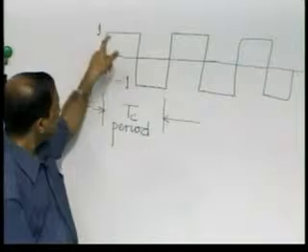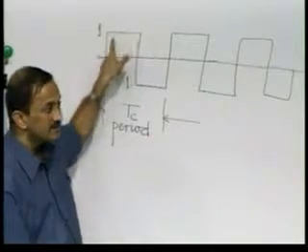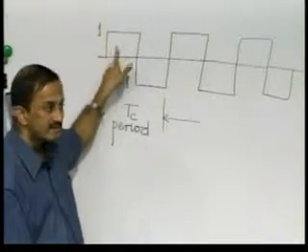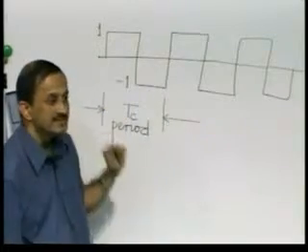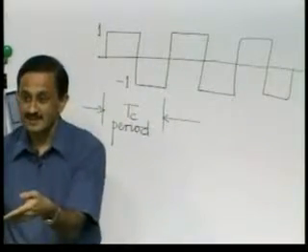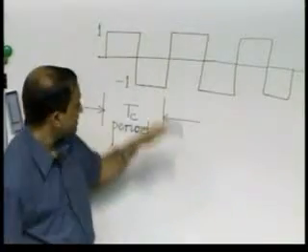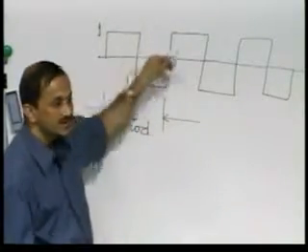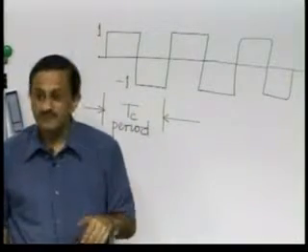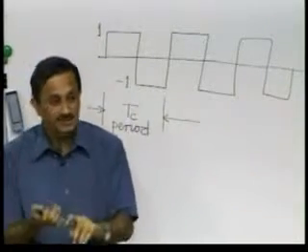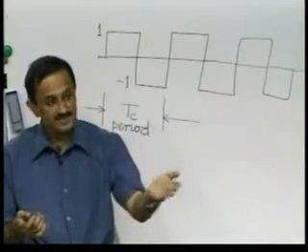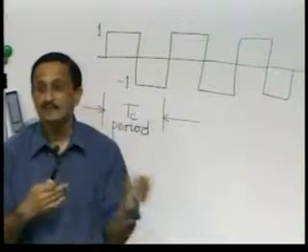So, here in this subinterval it passes the waveform as it is. In this subinterval it passes the waveform inverted. And of course, here there is no region where it does not pass the waveform at all, but suppose this waveform were to be 0 in some interval, then that is the place where the waveform would be blocked. So, either block or pass it as it is or pass it inverted. That is what a gating pattern does.